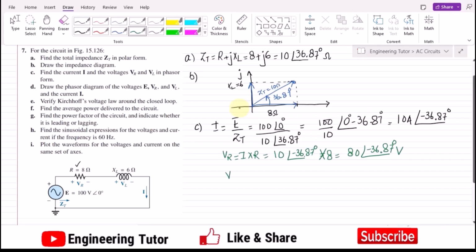Now in order to find the V of L, I have to multiply the current with JXL. The value of I is again known, 10 with minus 36.87 degrees, multiplied by the X of L. The value of X of L is 6, but J is included with it, and I have told you that whenever a quantity includes J, or is imaginary, we write the magnitude and the angle with it is 90 degrees.